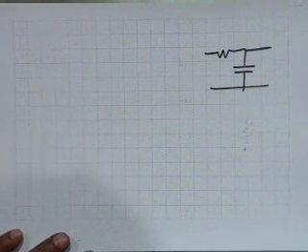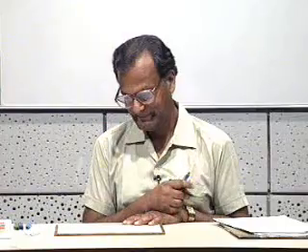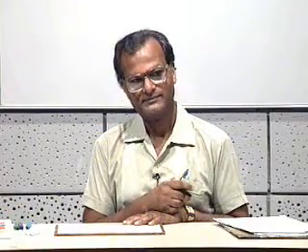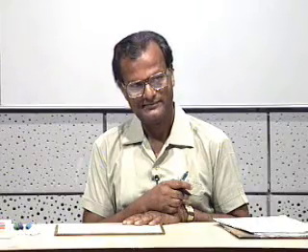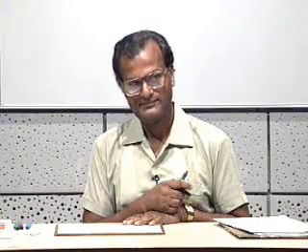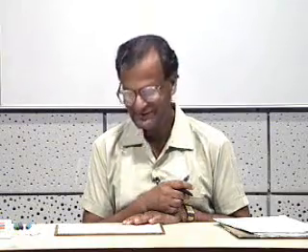Alright. Sir? Yes. So even if somehow you were able to realize the ideal low pass filter, still the system which you have constructed, of what use is it, because that omega c is not some fixed value. Omega c will depend upon the highest frequency of the sampled signal. That is correct. So therefore different signals will need different systems. That is quite correct. It is application specific.